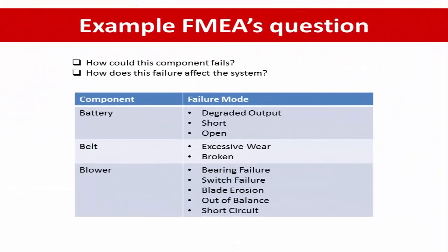Example FMEA question. FMEA, or failure mode and effect analysis, or FMECA, failure mode effect and criticality analysis, is a methodology to study component failure. For each component, the review team will be asked the questions: how could this component fail? How does this failure affect the system?